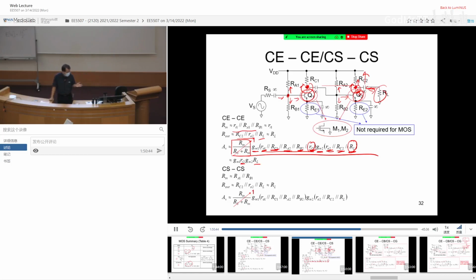I want to design an amplifier that has gain, but you've got 10 factors. How do I choose? Too difficult. So instead, you decide, out of all these things, let's make a few dominant. GM, dominant, right? Out of all the resistors, RO2 is limited to the transistor, so let's make it dominant. The other resistors I can pick anyhow.